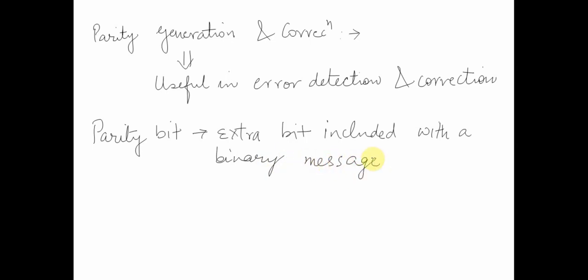Let's look at this. Let's assume that I have a three input signal called X, Y, Z, which can have these set of values. I'm just quickly writing them down. Now let's assume I add a parity bit, P, and let's call it an even parity. Even parity in the sense that if we add this bit into the circuit and we XOR X, Y, Z with P, the output would be an even parity. So let's assume we have an even parity bit. So the output of this is 0.